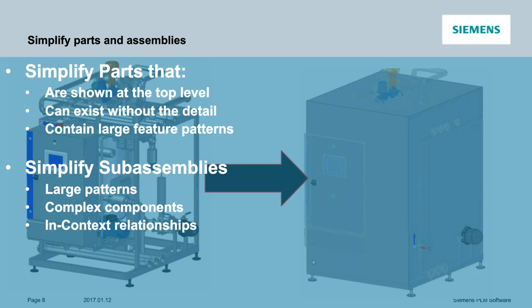Okay, we'll talk a little more about simplification. Simplify complex shapes into simpler, primitive shapes. You cannot see most of the detail of individual parts at the zoom level required to see the entire assembly. So as I mentioned before, remove the threads from the bolt. You really don't need that. In fact, volumes of CAD Bibles have been written about the best practice for modeling parts, especially in history-based CAD, where your entire experience with performance is based on following best practice tightly.